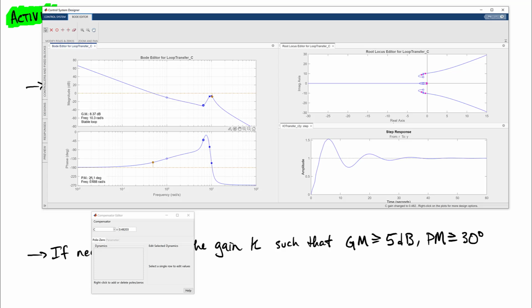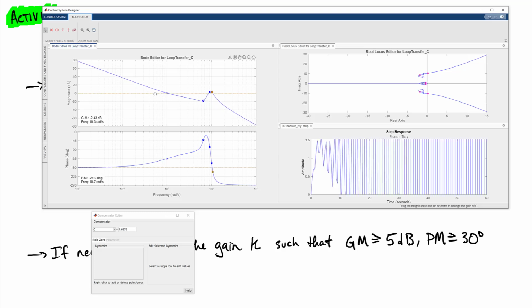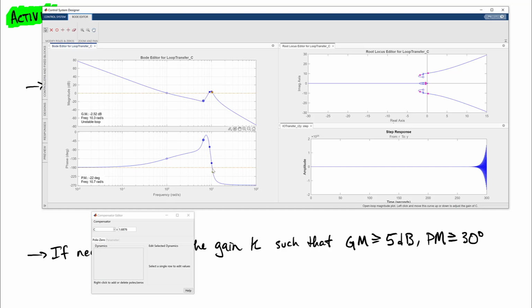But we notice that now we've been messing with our phase margin, and so now we need to identify what values of the gain satisfy this phase margin. So you notice as I'm increasing the gain, I'm getting better and better phase until I jump over here. Notice now we've switched which 0 dB crossing results in worse phase. So up until some point, we get some good behavior. But you can see here we're getting well over 30.